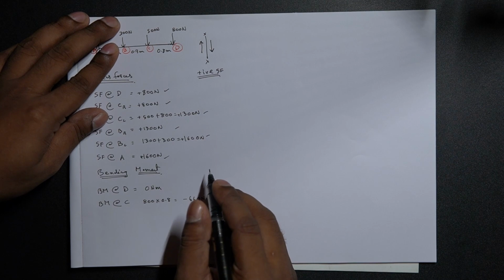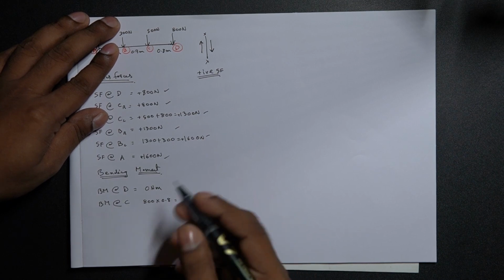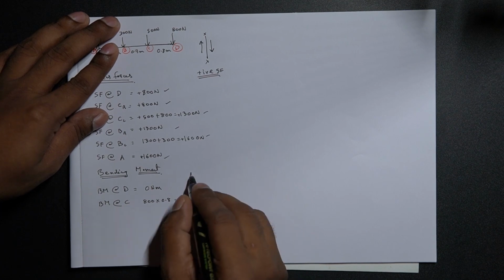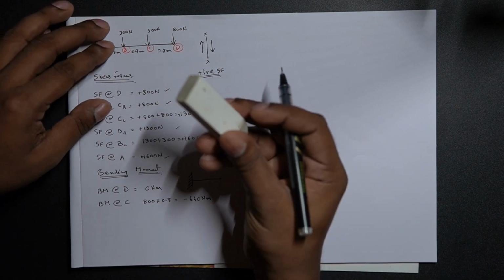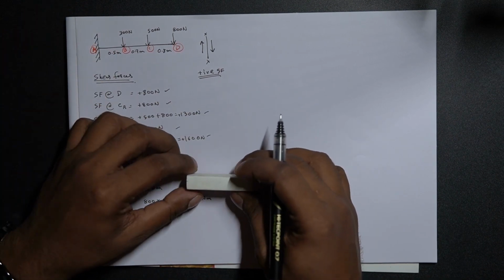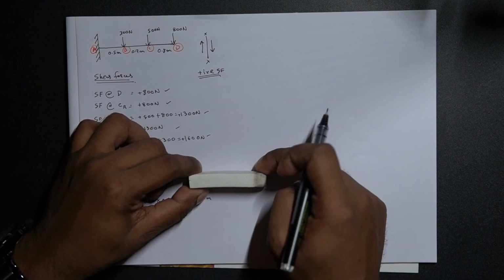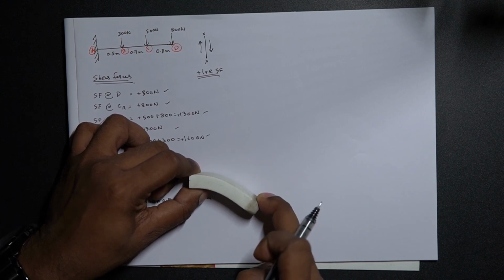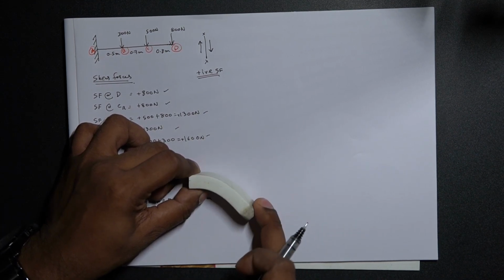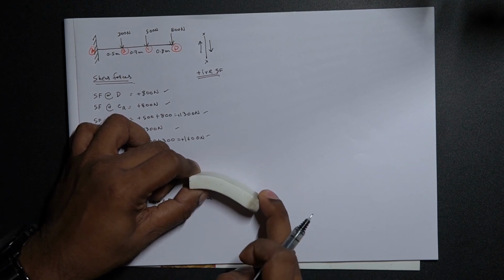The second form is the movement in terms of clockwise and anti-clockwise directions. For instance, let us just consider a fixed support with a cantilever beam. Now I'm just considering this eraser as a beam section over here. If this is the fixed section and this is the free end, and I am applying a load, if there is a hogging action in the cantilever beam, that is, the beam is hogging, we consider the moment to be negative.